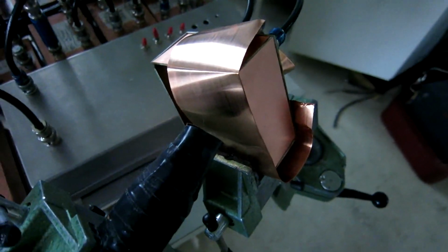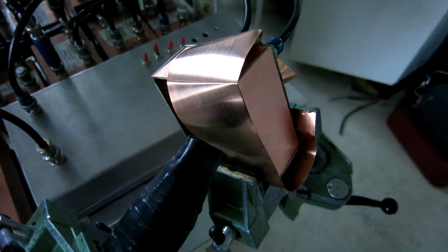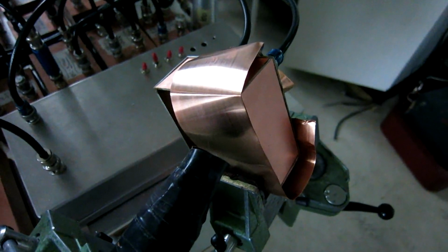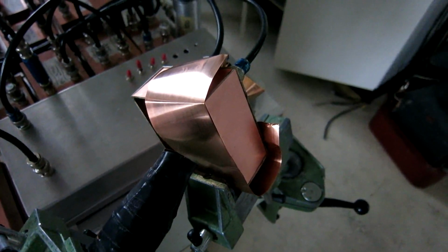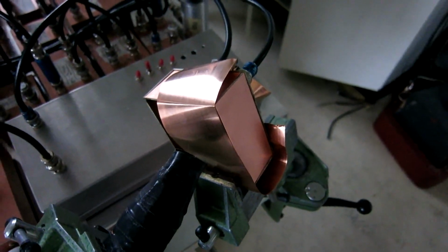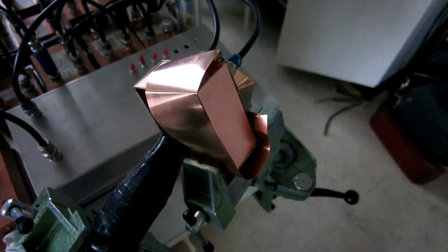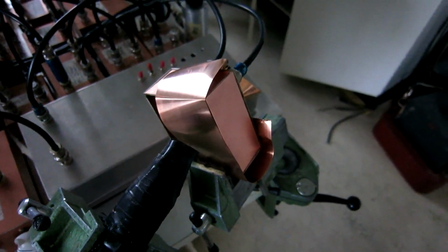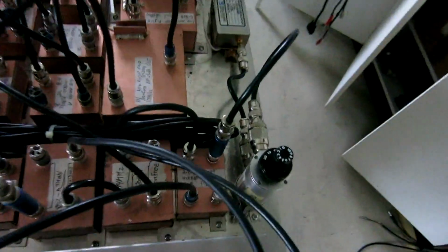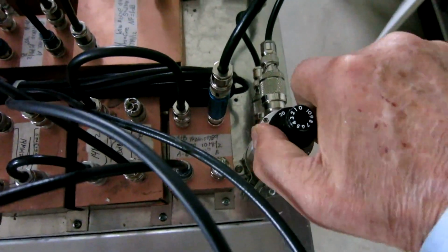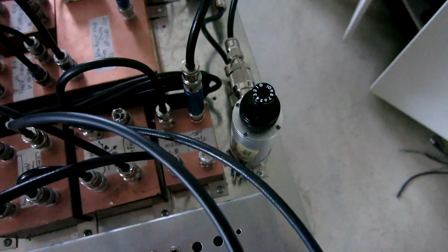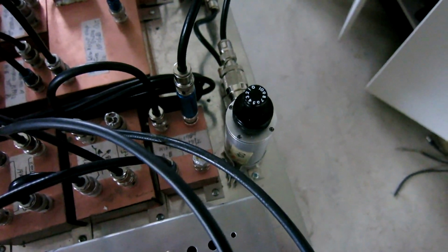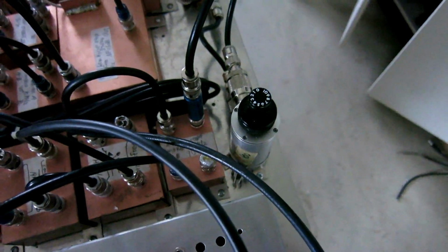Here is where I will place the device under test. At this time there is no crystal inside, just a wire. So first I am looking at the properties of the setup itself, with no object to study. And first I'm running it at full power, 12 dBm, but now I change this by inserting 20 decibels of attenuation into the interferometer to look at where the noise floor now will come.